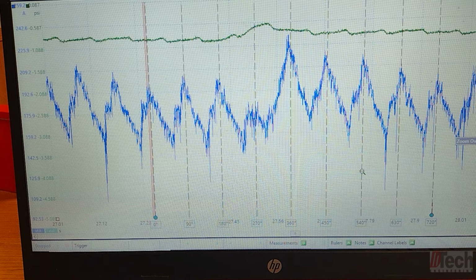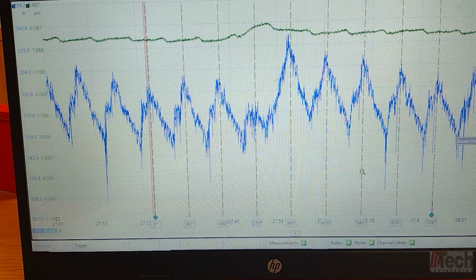Now we've been on this vehicle, as far as testing, not even a half hour, just a few minutes of setting up and doing this quick test, and right off the bat, based off of the misfires that they were complaining about, we already know that there is a mechanical engine issue, and in reality there is no need to continue. We can accurately give the customer a good positive estimate as far as what it's going to take to repair this, and there really probably wouldn't be much more testing to do.